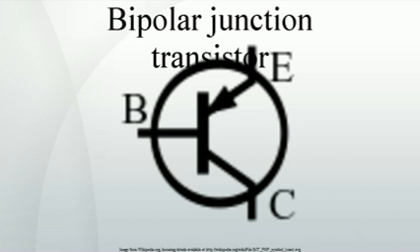Forward active, or simply, active. The base-emitter junction is forward biased and the base-collector junction is reverse biased. Most bipolar transistors are designed to afford the greatest common emitter current gain, βF, in forward active mode. If this is the case, the collector-emitter current is approximately proportional to the base current, but many times larger, for small base current variations.